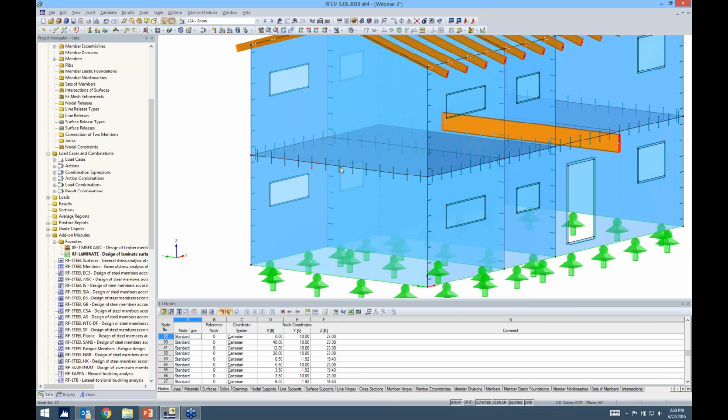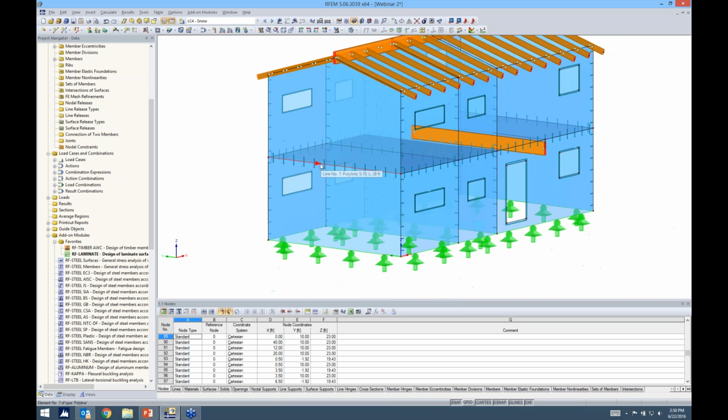Now you might ask yourself the question, well, I see two line hinges here, but the reason why is because my floor panel is also framing in here, which doesn't have a line hinge. Therefore, we're stable for this particular intersection.